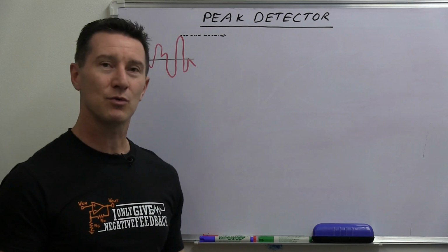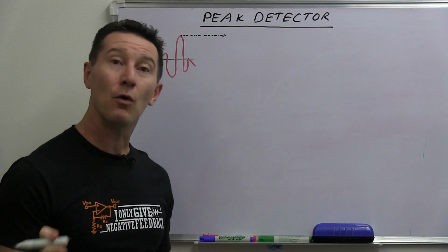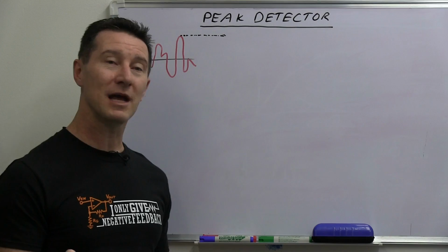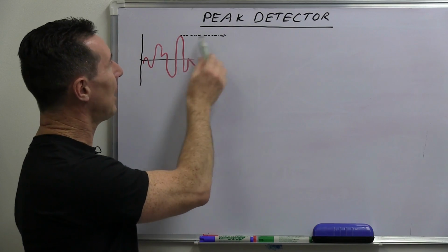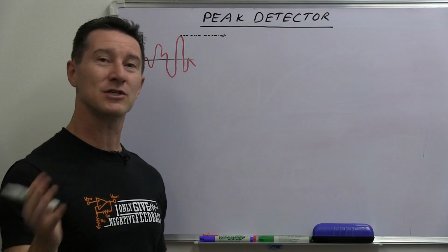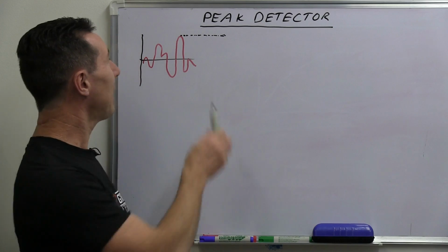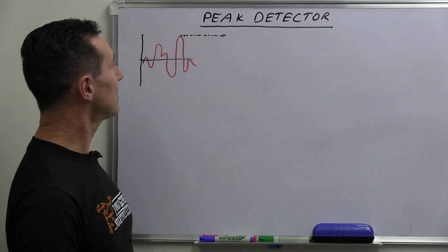Now, why would you want to do that? Well, there's many reasons in the audio field. For example, you want to get a peak value and hold it there. You might want to drive some sort of LED display or something like that. Lots of measurement scenarios as well, where you may want to get this peak detector value.